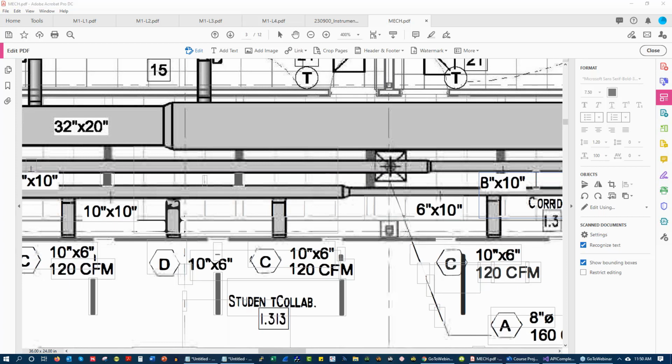As a facility manager, when should one get involved in the BAS process? So that's a good question. Ideally, you would have a BAS standard, and that BAS standard would have standard sequences, standard point naming, standard drawings, standard graphics. Here's the thing. For every dollar or hour you put into creating a BAS standard, it's my experience that you're going to get $3 or 3 hours back.